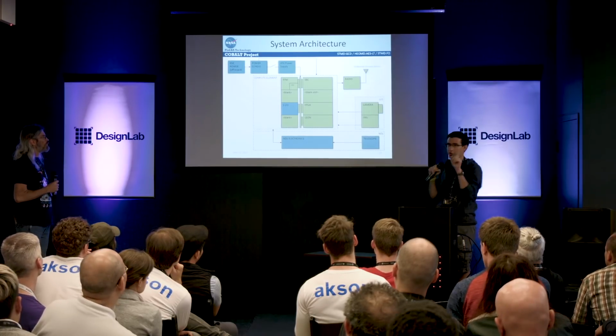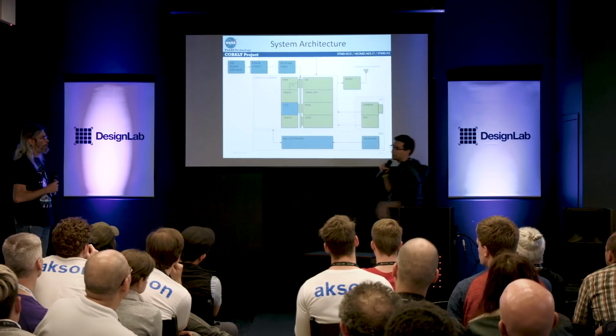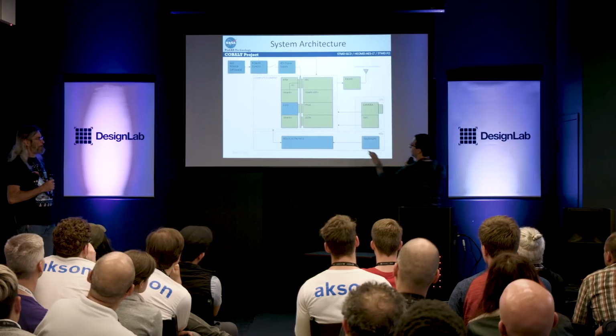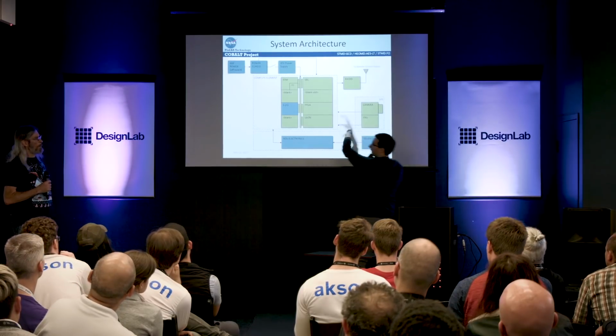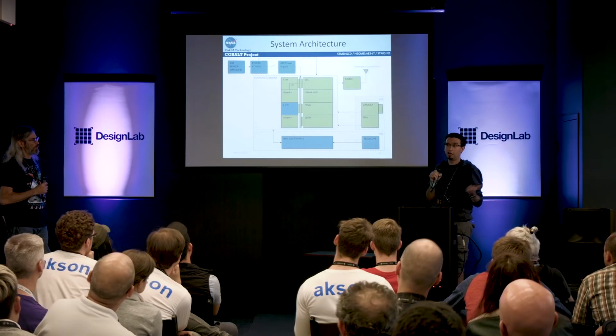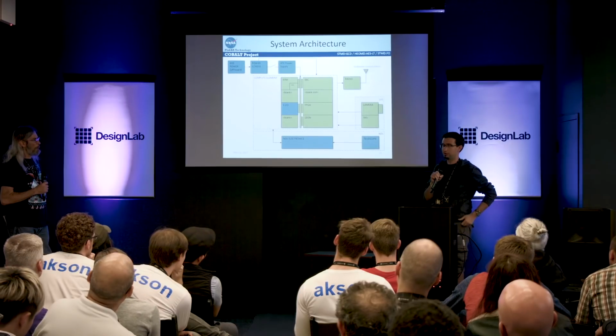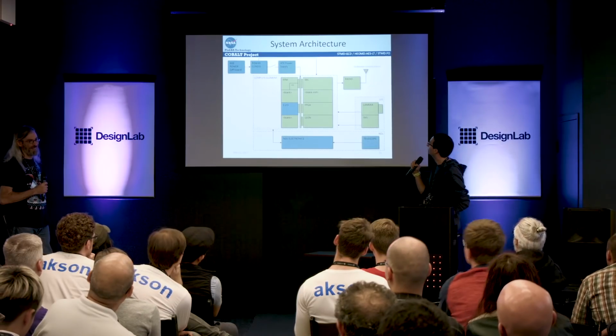So one note here, this is going to be important in a few slides. This little bar over here represents a backplane. All these various cards slide in and connect to this connector, kind of like a motherboard with a PCI. We used a standard called compact PCI, where there's nothing compact about it, as you'll learn really soon.